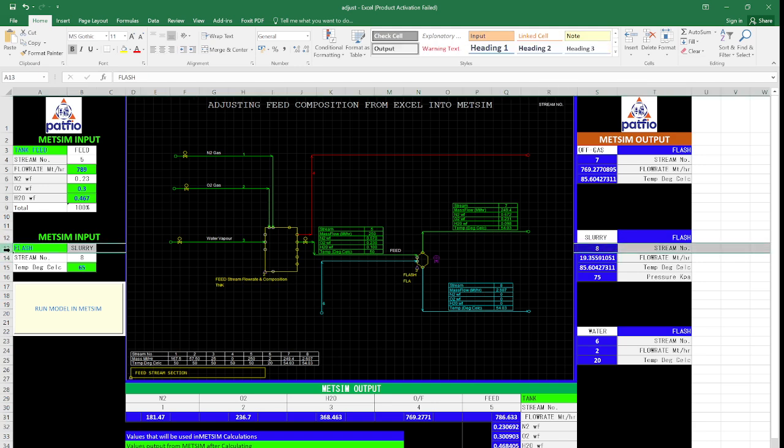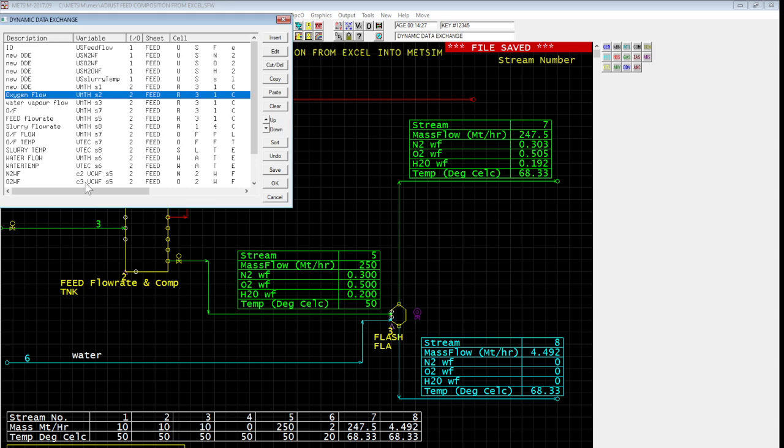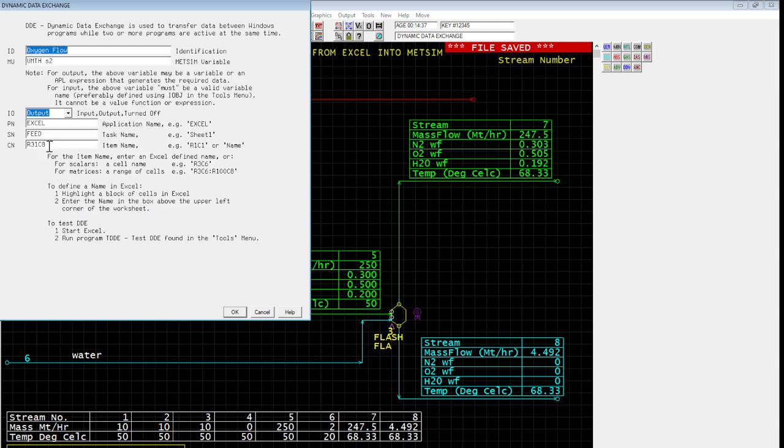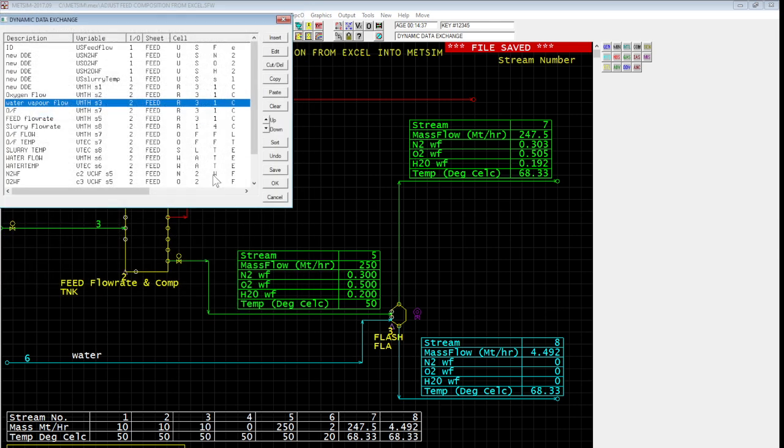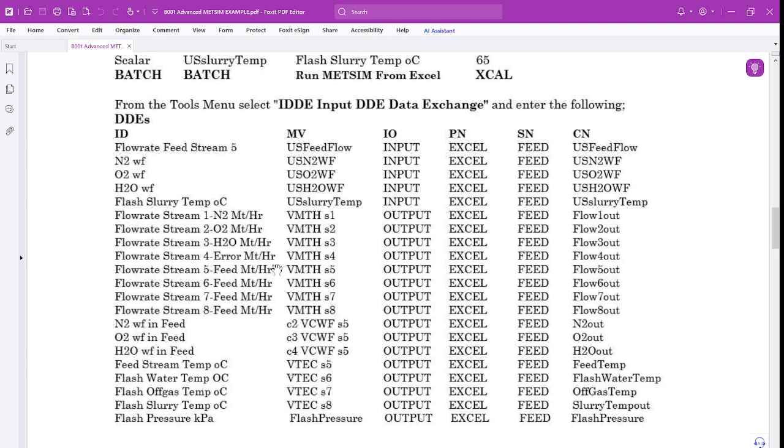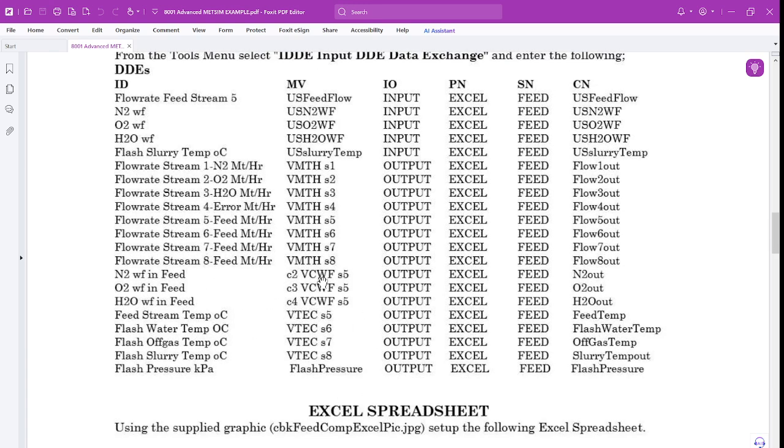In this case, it will be row 31 and a column number. You count the number of columns, then you insert the value here. So row 31 column 8, that's where the output is going to be stored. Then you click OK. You do the same for other outlet values that are going to be collected.